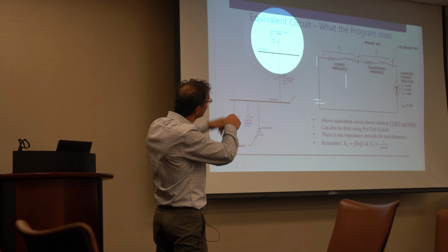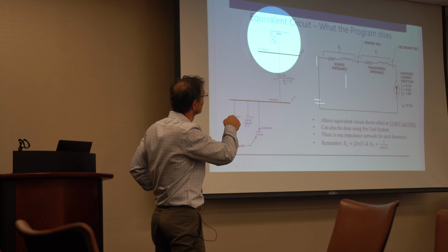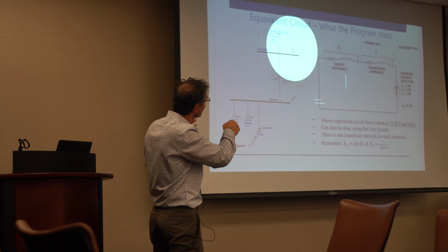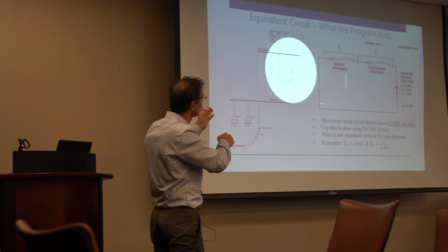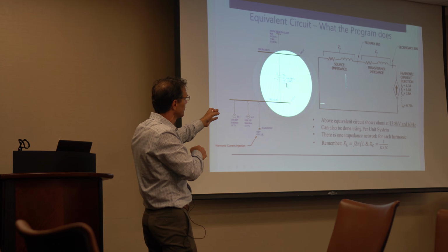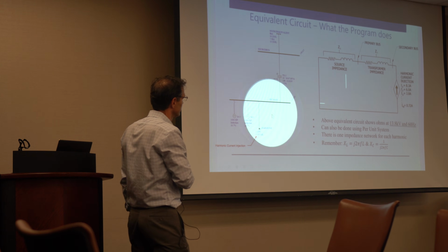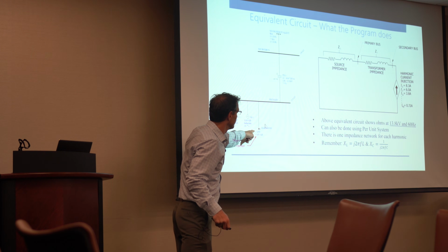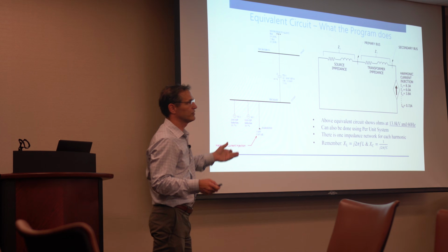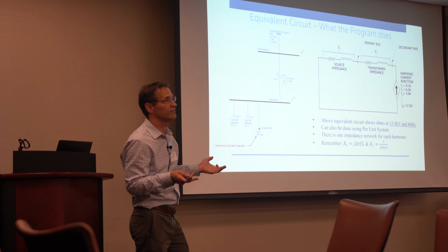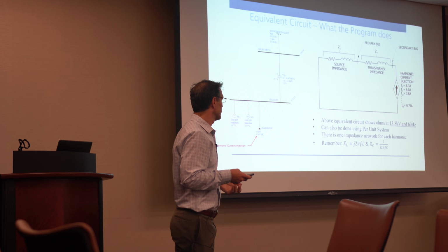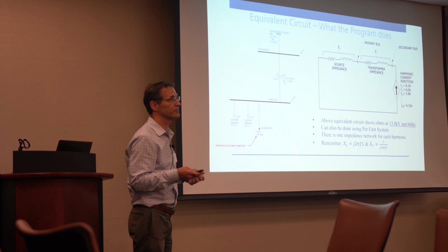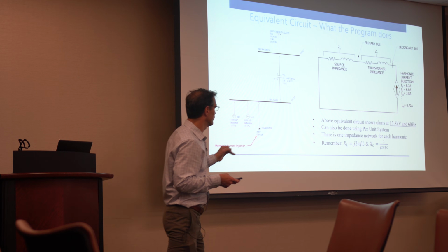So you have this source equivalent here, okay? 10 kA, it's a 7.5 kA, X over R of 13, 138 kV through a service transformer down to 13.8 kV, and we have a harmonic current source there. Here's 3 megawatts, 3 megavars. That's like a rectifier, equivalent to a 13.8 kV rectifier running at about 0.7 power factor, which is pretty typical. So that's what we did here.